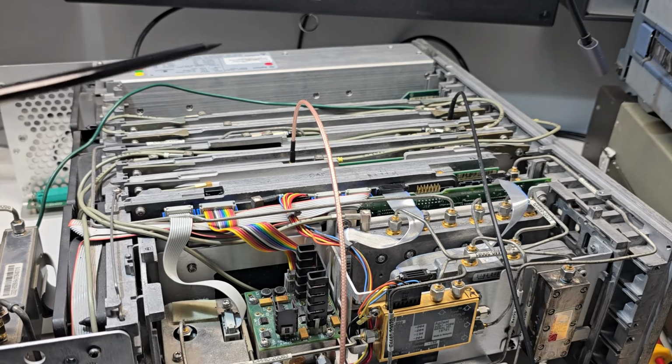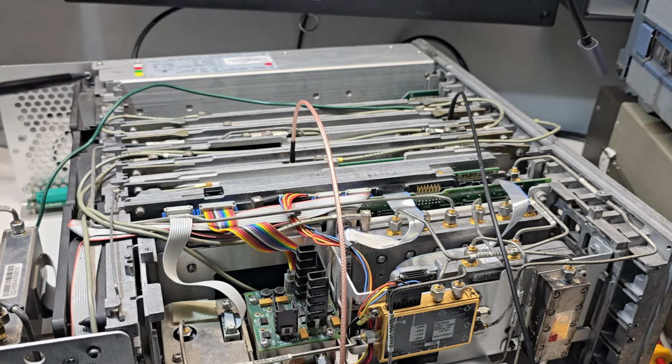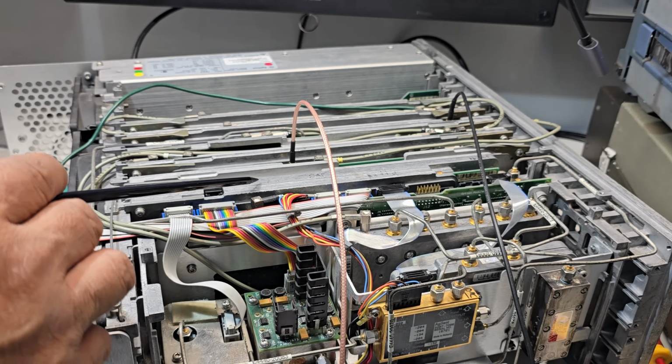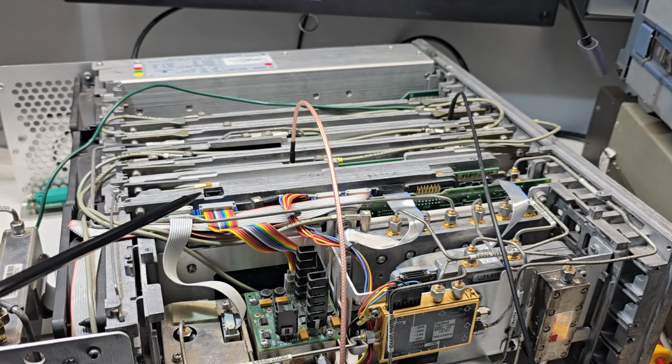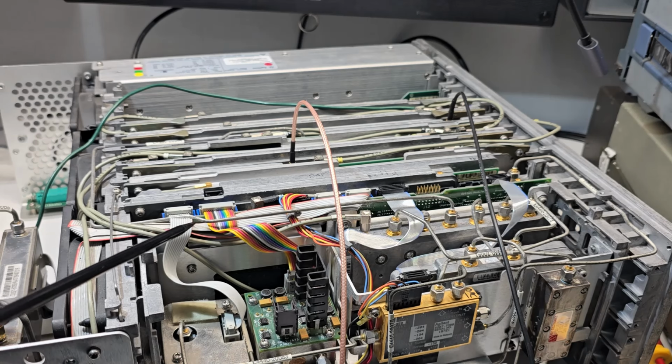Maybe there is a single transistor there or a monolithic transistor. This old unit might not have a monolithic, might have a single transistor to increase the output at 600 megahertz to 13 dBm. So if I find that the transistor is faulty, I'm also not sure if we could source that transistor because this unit is quite old, and there's a slim chance that I will be able to fix this unit.